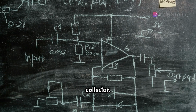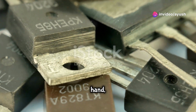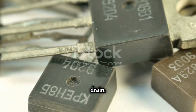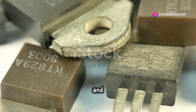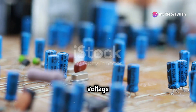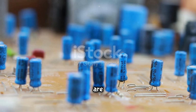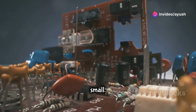When a small current is applied to the base, it allows a much larger current to flow from the emitter to the collector. And field effect transistors, or FETs. FETs, on the other hand, use an electric field to control the flow of current. They have 3 terminals called the source, gate, and drain. The source is where the current enters the transistor, the drain is where it exits, and the gate controls the flow of current between the source and drain. When a voltage is applied to the gate, it creates an electric field that either allows or blocks the flow of current. FETs are widely used in digital circuits because they consume less power and can be made very small.